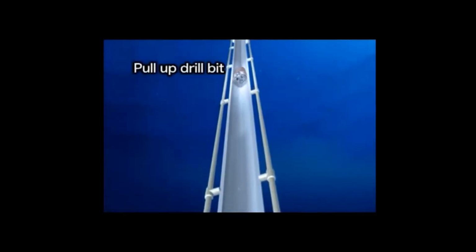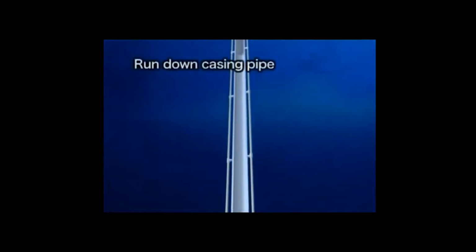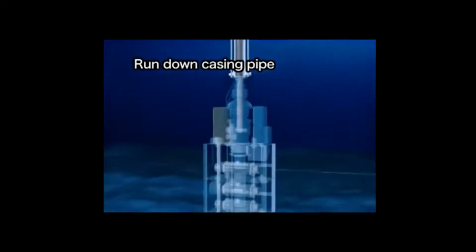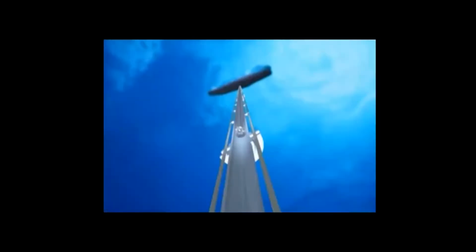When the target depth is reached, the drill bit is pulled back to the vessel. To drill the hole even deeper, a narrower casing pipe is set in to protect the drilled hole. After the casing pipe has been installed, cement is pumped into the space between the hole and the casing pipe to fix the pipe in place.